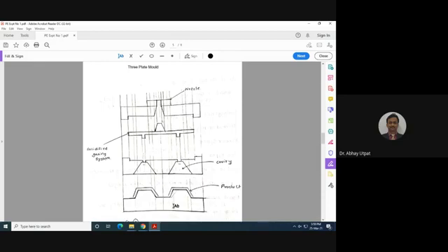So the first plate is here, the second plate is here, the third plate is here. In between the first plate and the second plate, there is a gating system. And in between the second plate and the third plate, there is a product. So imagination is required. Assume that all these plates are closed. When closed, there will be a gap. In this gap, this product will be produced.